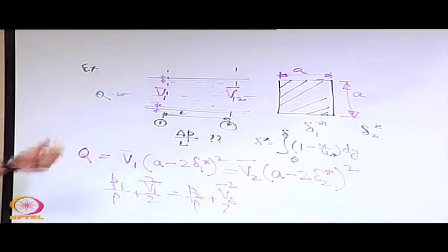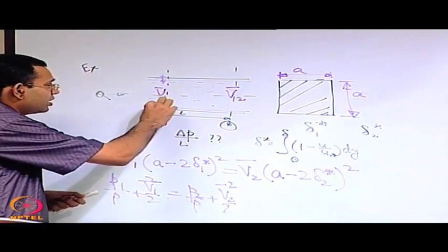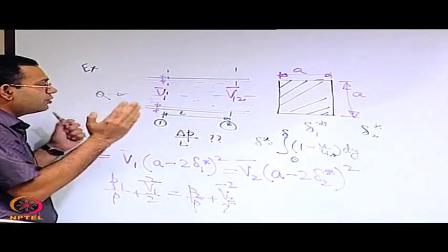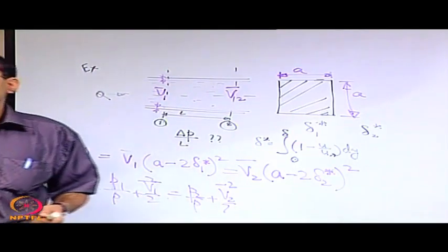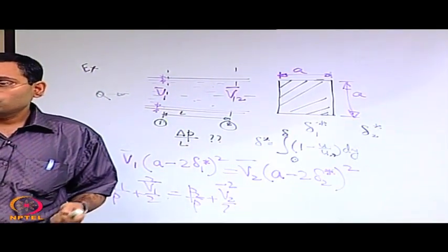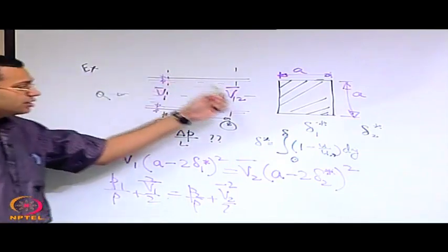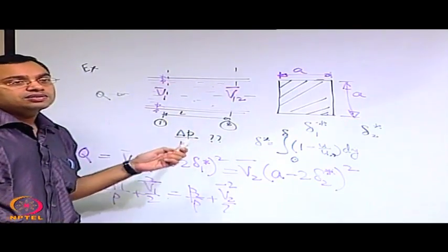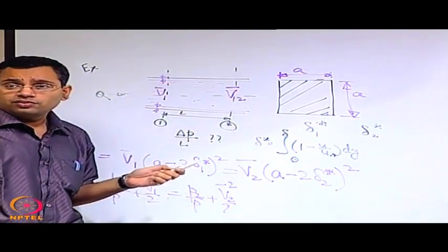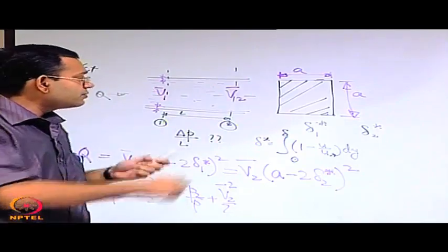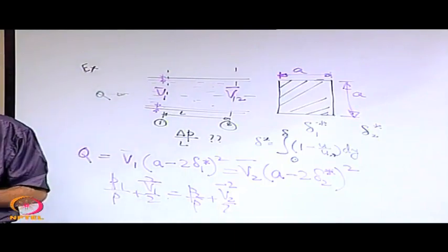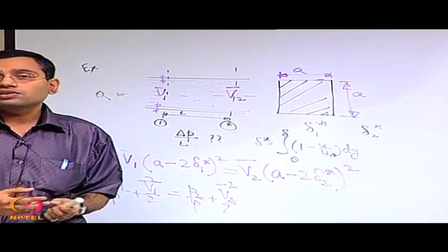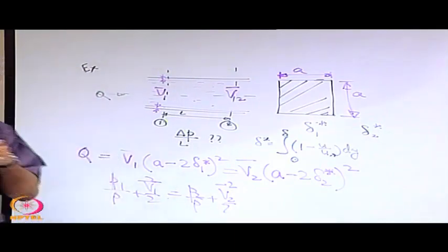But what is our expectation in these cases whenever we have almost presumed that the boundary layer is very thin? It is that the Reynolds number is very large. So in these cases we are looking for experiments of large Reynolds number flows. Towards the end of such discussions we will come into cases when the Reynolds numbers are very small, and we will try to see what the corresponding demarcating features are.